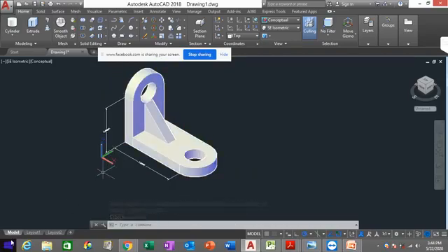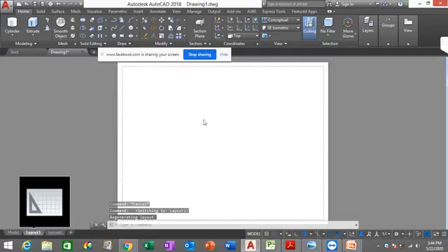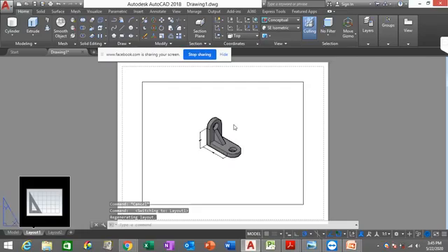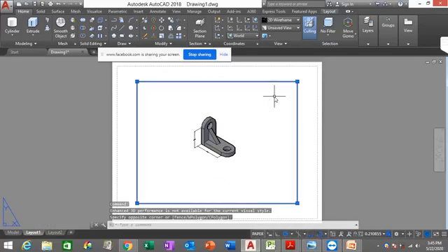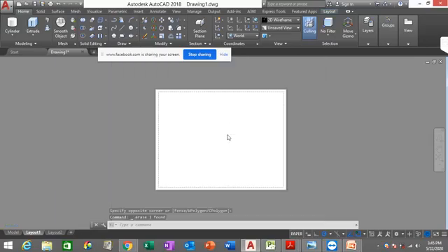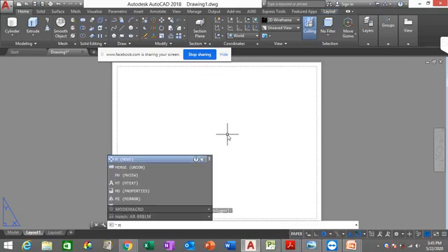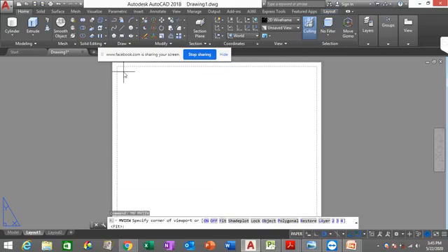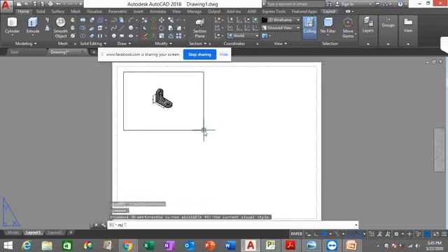Then if you want to print with AutoCAD, if we click layout, it will give one viewport. One viewport like this. But actually we can control that viewport. So I don't want the original viewport setting. I can select and delete this viewport, like normal deletion. Then I can manipulate this by creating more viewports by typing MV, enter. So type MV, enter. I create as many viewports as I want.